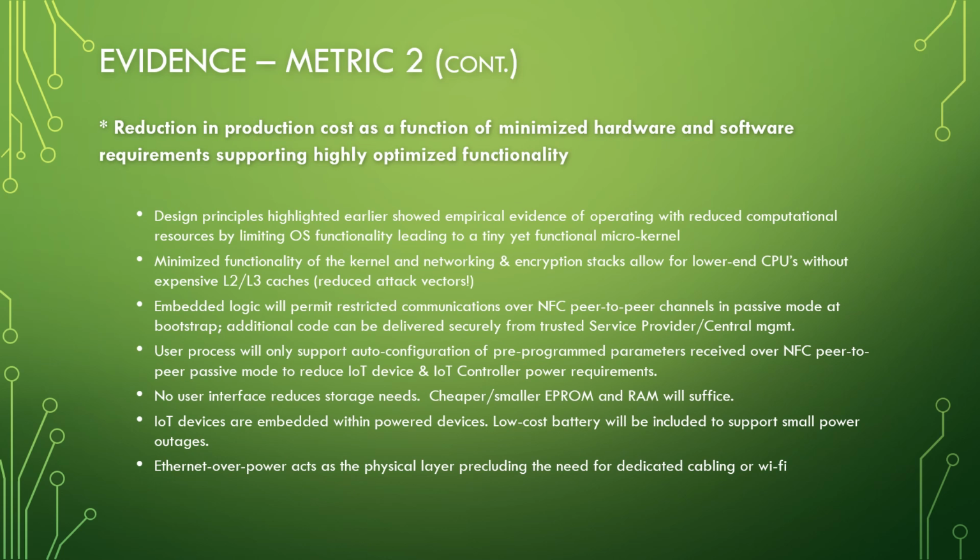The bootstrapping processes do not need to be large and can actually support a network-based OS load. For example, a basic EEPROM might be all that's necessary to collect the basic config and symmetric key. The fit-for-purpose protocols for setup can be made proprietary and make it harder for attackers to keep up, and the need for non-volatile storage may be eliminated due to the use of operating systems being loaded over the network, but it's more likely that it could be reduced at least in size.